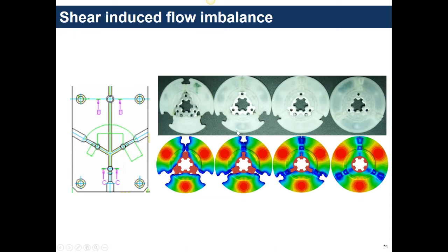Okay. Now that you're able to simulate this and capture the problem, now you can start thinking about solutions on how to solve this problem. So you could end up with something like a melt flipper or a mixer in there to try to distribute the temperature a little bit better. Or you could try to make your runners bigger, because again, the problem is happening because of viscous heating. If you make the runners bigger or go with a lower viscosity material, or if you slow down your injection velocity, you may be able to solve this problem without really adding any sort of a device in there. But once you have the ability to simulate it, you can then figure out the best solution for your project.